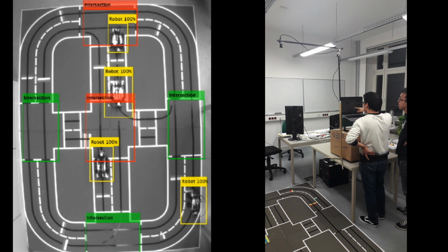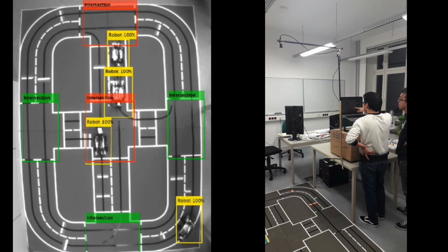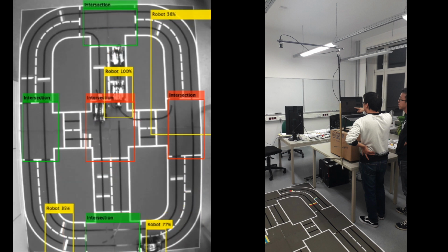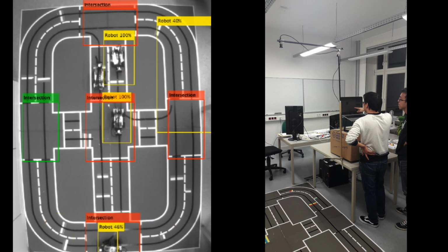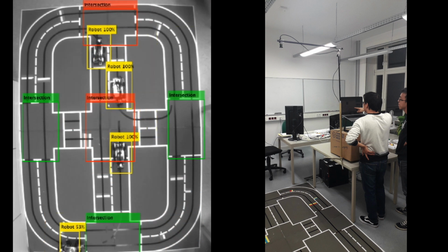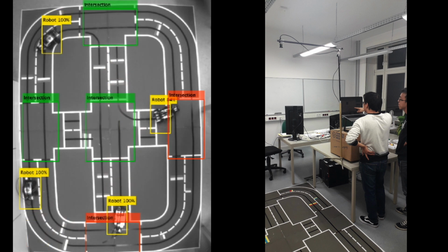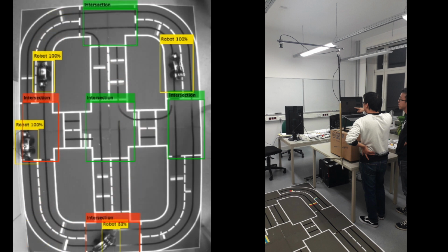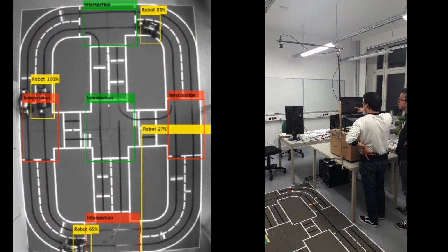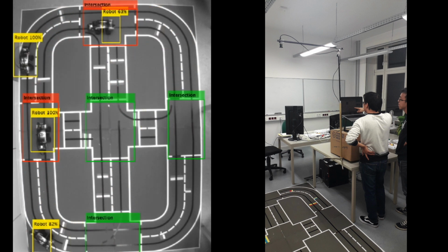Then, he has trained the detector using the created ground truth data offline on a single robot video that we have captured with our camera. Next, we have tested its performance on a video of two robots and modified the algorithms to get a clear bounding box of the detected vehicles. In the end, we have decided to use an ACF detector for this project.